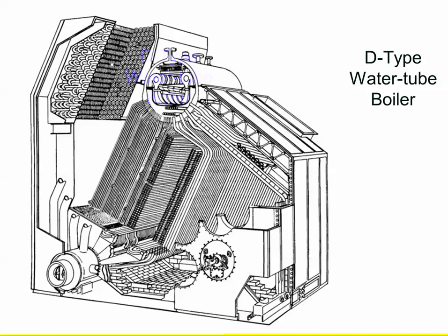Now, on light off, typically I'll ask the students, what's protecting the superheater tubes? And they'll say, well, it's the superheater vent. And I'm going, well, you have no steam. There's no flow. You just lit off. The answer to this is nothing.